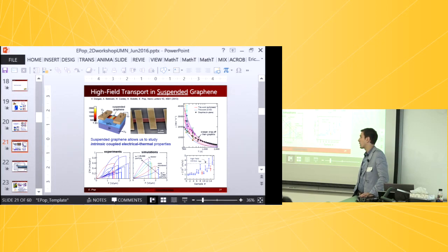You're not going to be able to get rid of the thermal component in pulsed measurements because this is just too fast thermally. The heat will get out in less than a nanosecond, so there's just no way we can do pulse measurements. So from a thermal point of view, these measurements are always steady state. But electrically, yes, if you have charge trapping, of course, pulse measurements will help. Yeah, I was thinking thermal, but you're right.